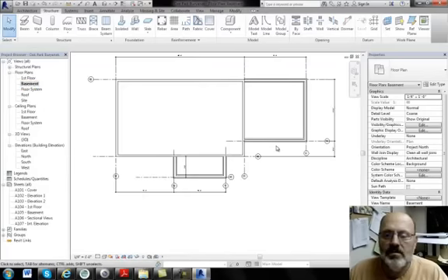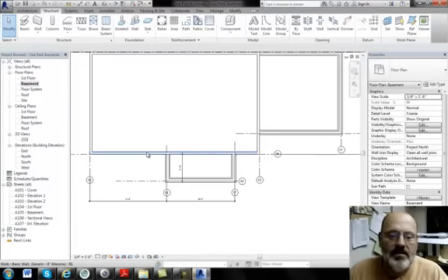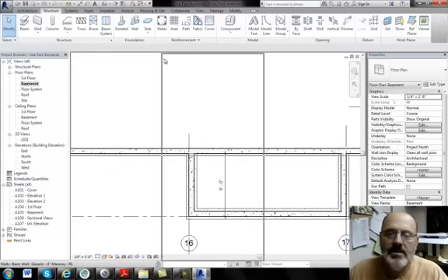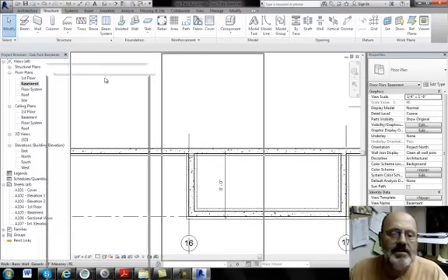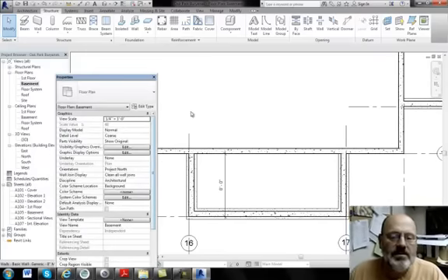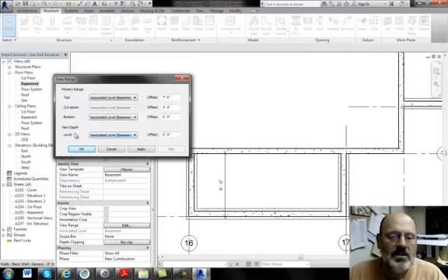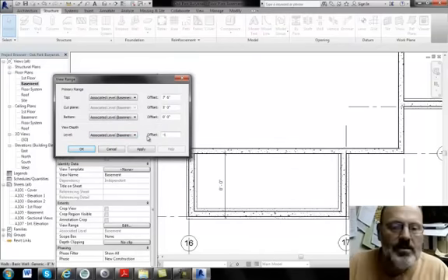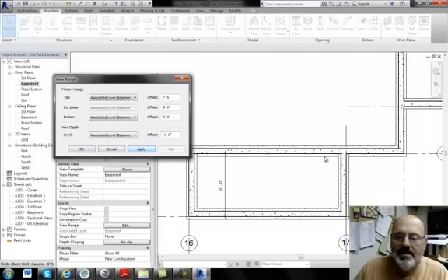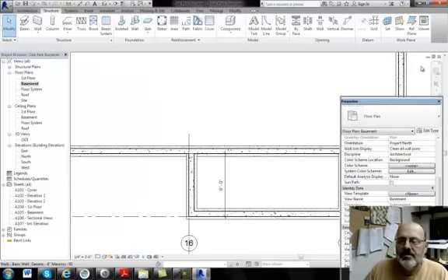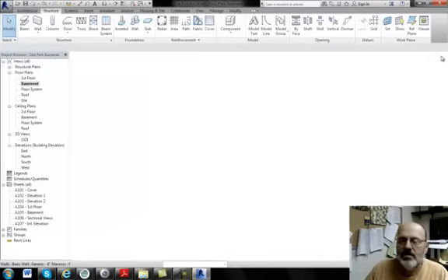Back to the basement view. The footings show up here. They don't show up here. Once more, we need to edit view range. Change one thing on the view range. Nothing can be selected. Edit view range, and on this associated level view depth, put it at, I think, -1 will work. That's 1 foot. Yep, then they'll show up. So now we have our basement walls and our footings for our stoop.